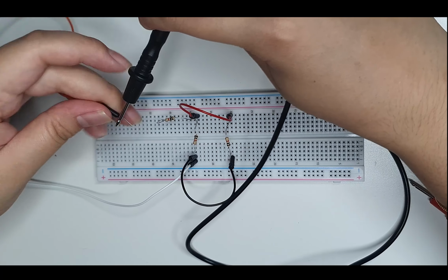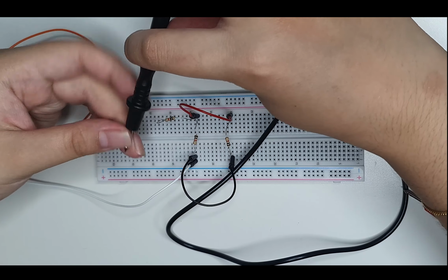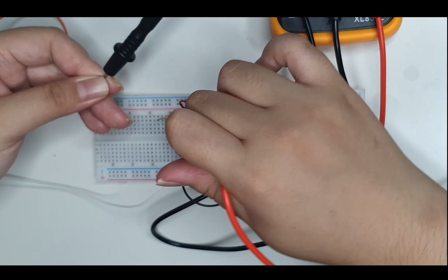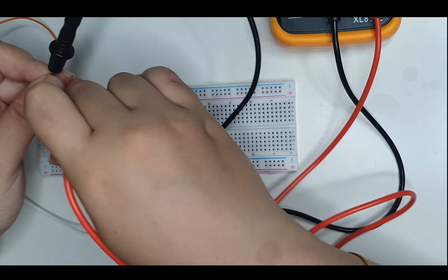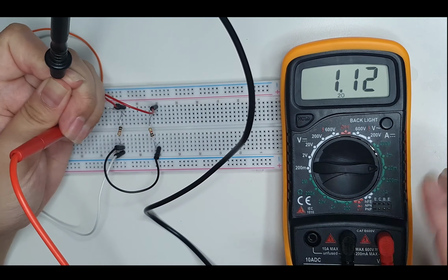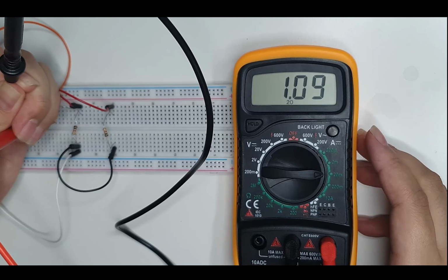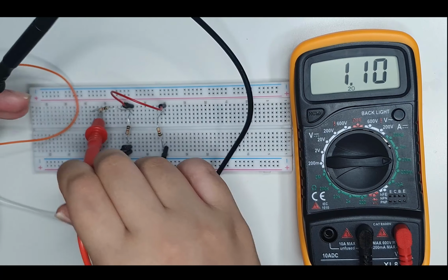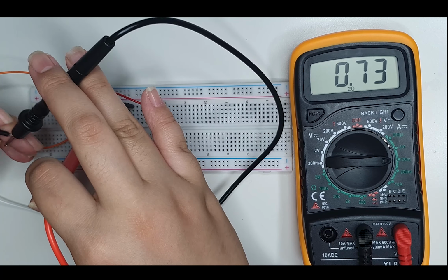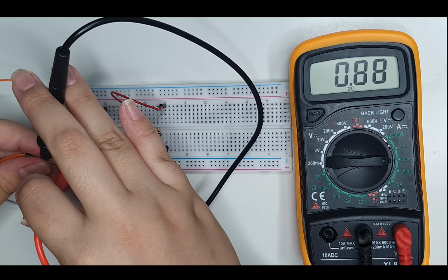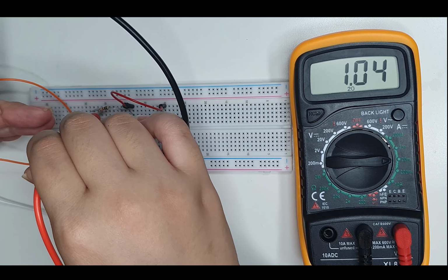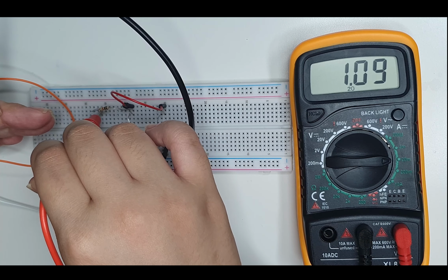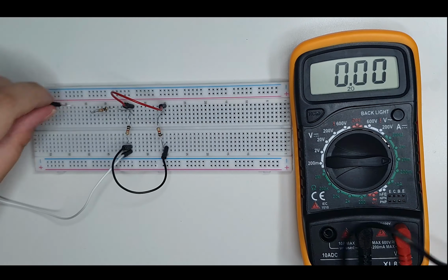Next, I will be measuring the total current. We know that elements in series have the same current value, so therefore current will be measured in series and not in parallel, like how I measured voltage just now. So I will be opening the jumper wires to measure current. So this is the total current for this circuit.